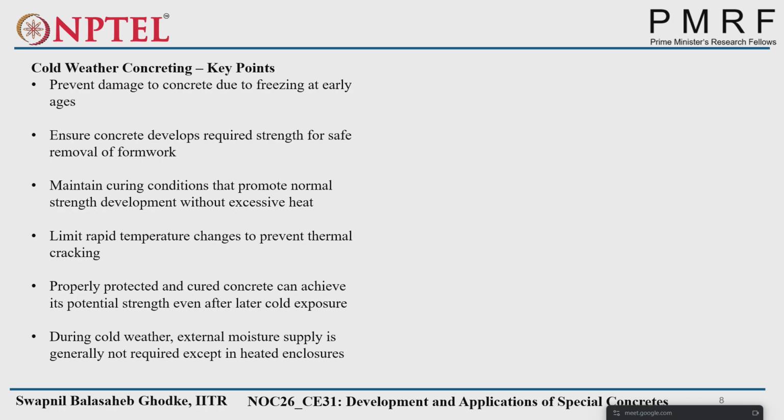So, what are the key points we have to remember? To prevent damage to the concrete due to freezing, it's most important to take care of its early stages, to ensure concrete develops the required strength for safe removal of formwork. So, before removing any type of formwork, we have to understand whether the concrete has set properly or not.